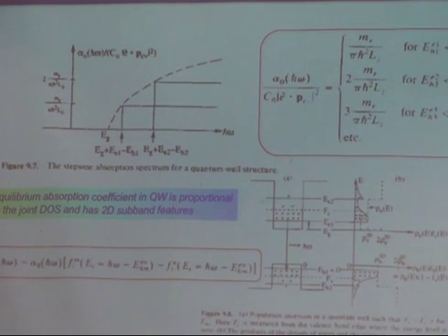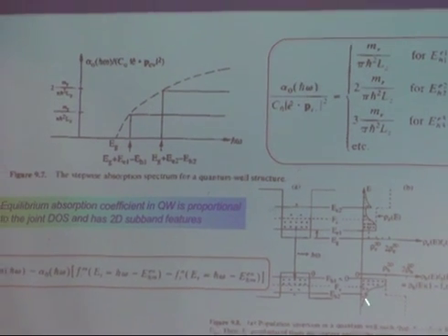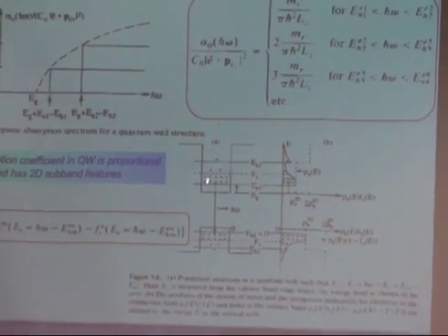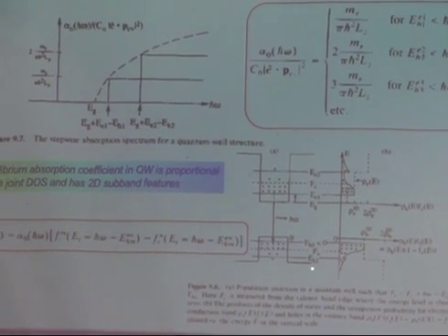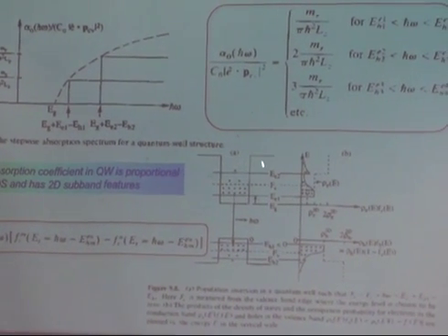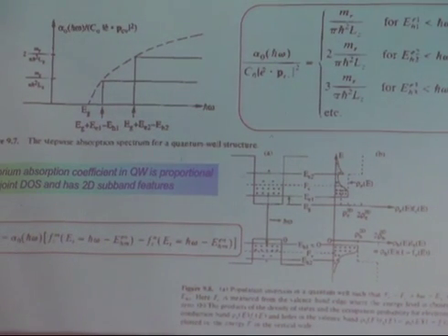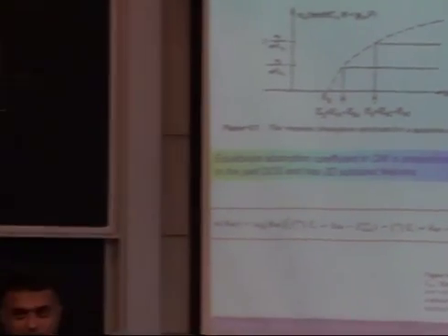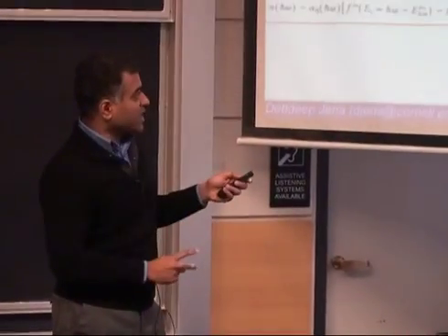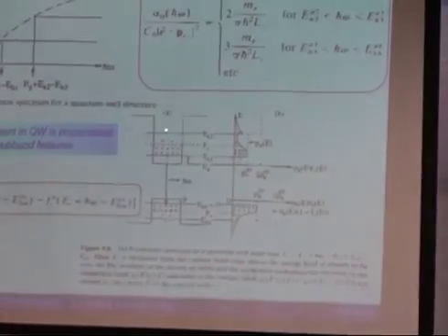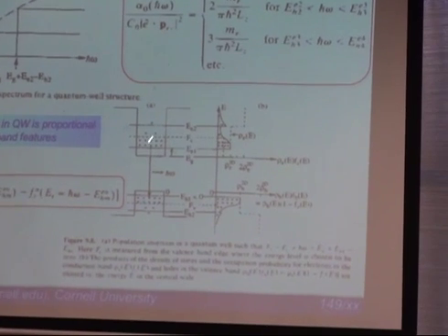So if you inject carriers, typically what will happen is, let's say you have an N side here, you inject electrons, you have a P side here, inject holes, and you fill these states with electrons and those states with holes. And because you have not just one subband, you can have two subbands, you can decide on the quantum well width and the height, which is the band offset, right? Depending upon your choice of compound semiconductor, you can fix those. If you have, for example, two subbands, two eigenvalues, two bound states, then you inject electrons and holes.